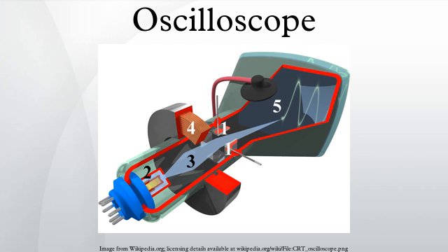Graticule. The graticule is a grid of squares that serve as reference marks for measuring the displayed trace. These markings, whether located directly on the screen or on a removable plastic filter, usually consist of a 1 cm grid with closer tick marks on the center vertical and horizontal axis. One expects to see 10 major divisions across the screen. The number of vertical major divisions varies. Comparing the grid markings with the waveform permits one to measure both voltage and time. Frequency can also be determined by measuring the waveform period and calculating its reciprocal.